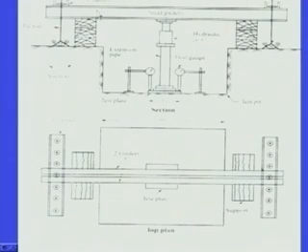Now, these are like ISHB or ISMB channels. Deformation of this plate due to the loading is determined or measured by the deformation dial gauges. 4 dial gauges are used, or sometimes at least 2 dial gauges are placed diametrically opposite to the test plate. The plan of this setup is shown in this figure. Now, these anchors are fixed by nut and bolt arrangement here.